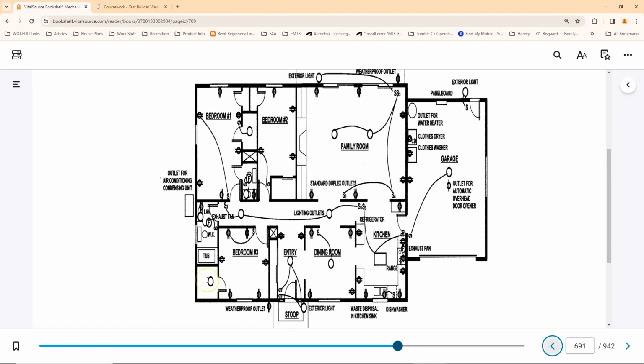It's just constantly powered, and we can either turn that on and off with a smart device or possibly even a motion detector device. But in either case, I would consider this a mistake, we really should be indicating how that thing comes on, regardless of whether it's a manual switch or a smart switch or a motion activated switch. If we are going to use a standard switch in this type of scenario, that switch can either go on the inside or the outside of the closet.